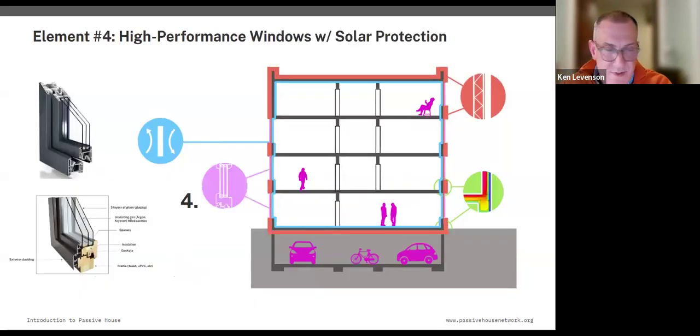It just really helps optimize in a bunch of different ways. So we've had the continuous insulation, the thermal bridge free construction, the air tightness, and now the windows and doors are continuations of those insulations and air tightness. So they're often triple glazed, triple gasketed, truly thermally broken.